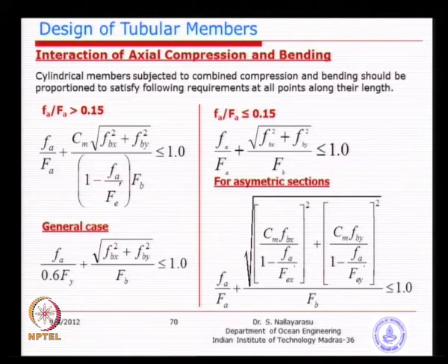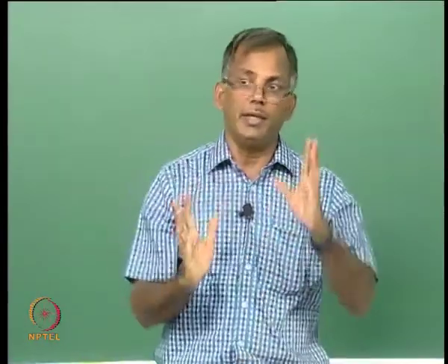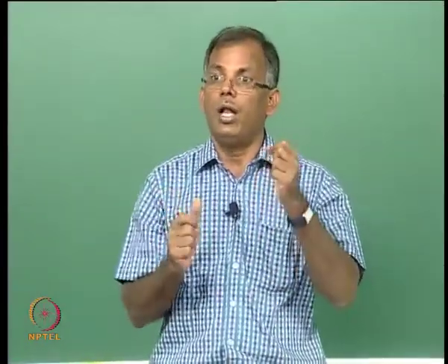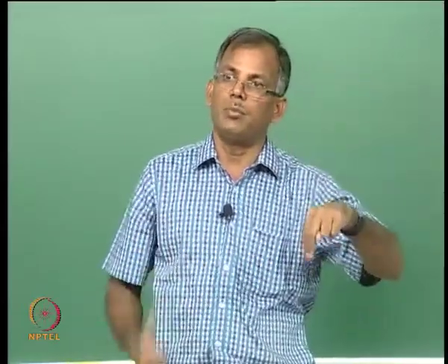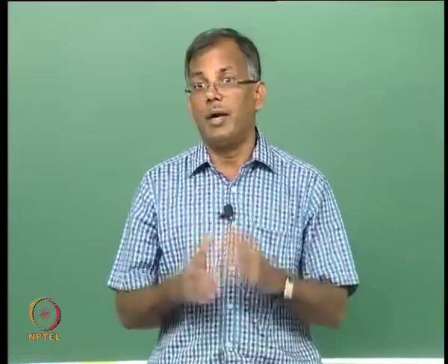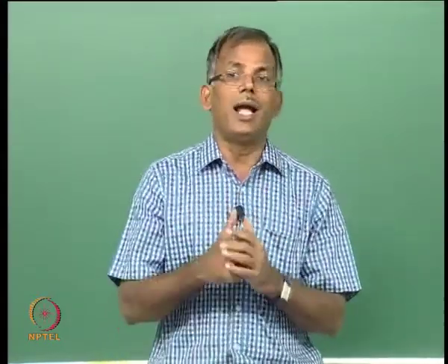So, what we have done is we have the axial component acting plus the bending component, but remember axial and bending stresses are in the same direction. If you have understood, axial stress is along the member length, bending stress is also along the member axis. The only thing is one portion will be subjected to compression, the other portion will be subjected to tension, but the stress direction is along the longitudinal axis of the member.